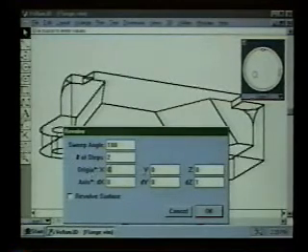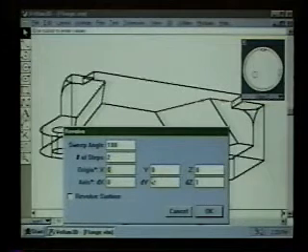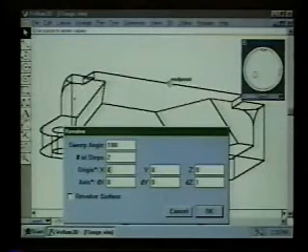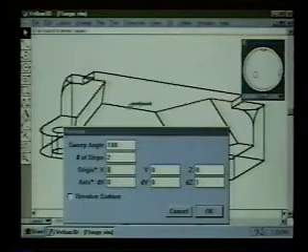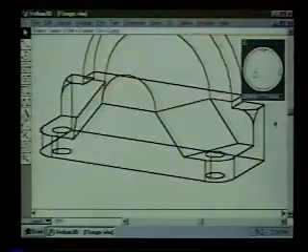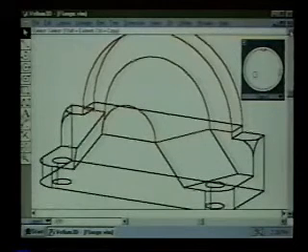And then, now here's 6 boxes. What do I type in here? I really have no idea. And it doesn't matter because I've got the asterisk here. And remember, anytime you see that, it means use the cursor to enter values. It's asking for the axis of revolution. Well, isn't it true that the axis goes from here, press and hold and drag, to there? When I let go, it fills in all these values. I say, OK, and there's my flange.